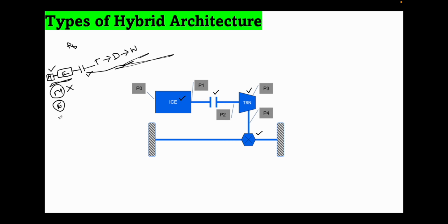Coming to the EM mode, engine and motoring mode, this is possible, because at that same moment you will be able to provide additional torque. What it is basically doing is assisting the engine to maintain the torque that it wants to provide. The driver will be able to get the power or output from the vehicle that he needs. Because of this, this type of architecture is being used. Mostly this will be assisting the engine. It cannot run separately in the electric mode. So this is about the P0.